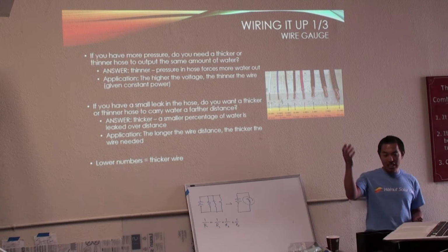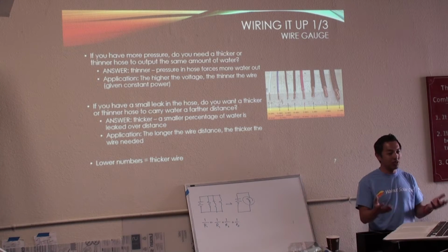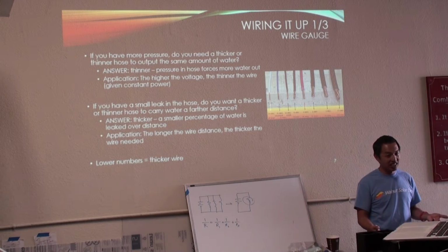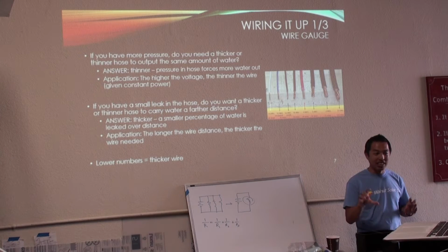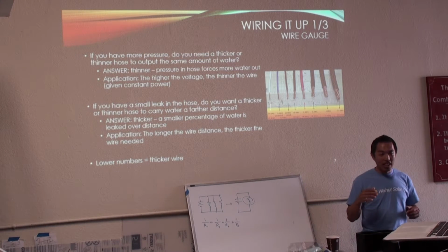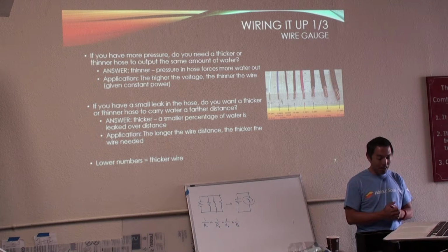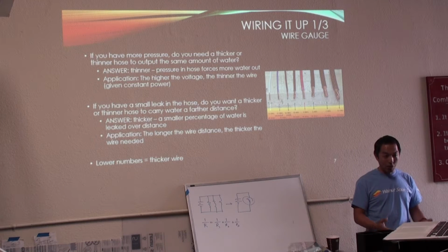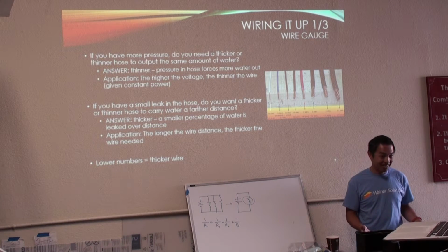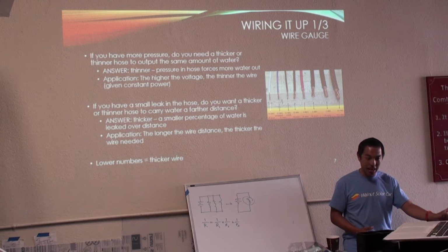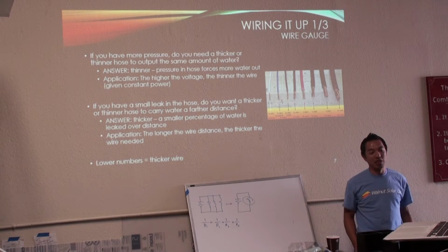So if I'm getting 10 amps coming in from solar, and I'm only using 8 amps, I'm positive 2 amps going into the battery, I'm charging. And so that's the effective charge or discharge rate. That's what net means. So if we're getting 15 amps of solar coming in, and we want to discharge at 1C in the battery, we actually can discharge at 25 amps, because you're going to get 10 amps or 1C from the battery, and you're going to get 15 from the solar, and then you combine that together.